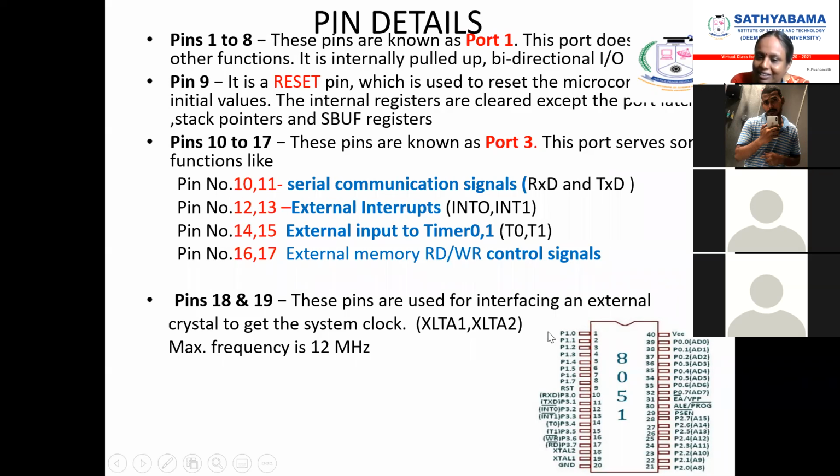So they have given the port in this way. Can you understand? These ports don't have any other functions. That means you have understood that we have an internal pull-up. What is pull-up? Pull-up, pull-down. Pull-up means we have a logic 1. Pull-down means obviously logic level 0. So you have understood these are pulled up, with logic level 1.